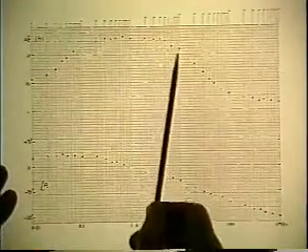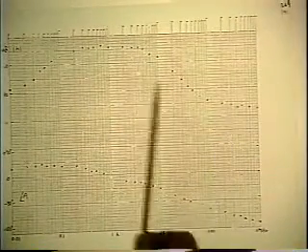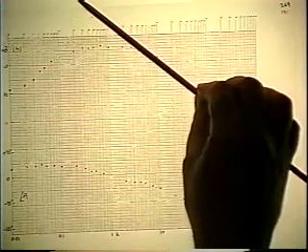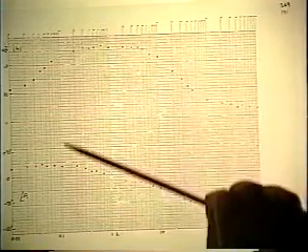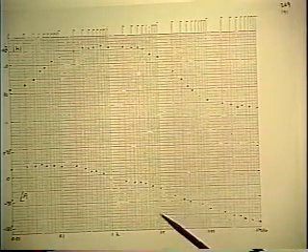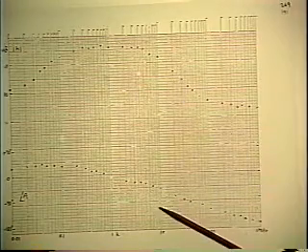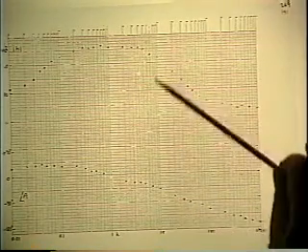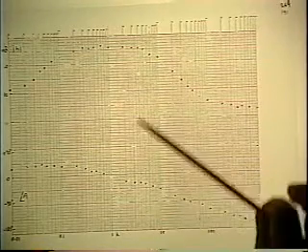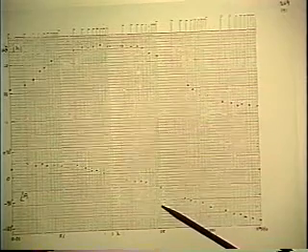Go back to the middle now. Obviously, some other things happen towards higher frequencies, and you do the same thing. And you have to end up with a consistency between the corner frequencies obtained from both the magnitude and the phase graph. So there's a fair number of constraints. You have to have multiples of the basic slope, and you have to have the same corner frequencies from each graph. Those are the constraints that enable you to get pretty accurate results for where those corner frequencies are.